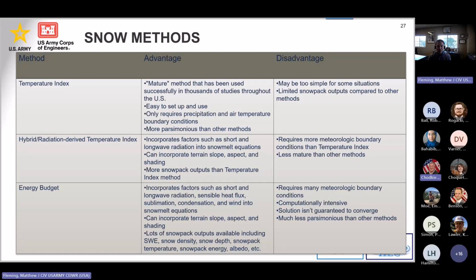If you're looking at a long-term forecast, months into the future, then your dry melt rate or your melt rate ATI function is important, and probably the base temperature. Right, so you can really reduce the number of parameters that you adjust based on the type of forecast you're doing.